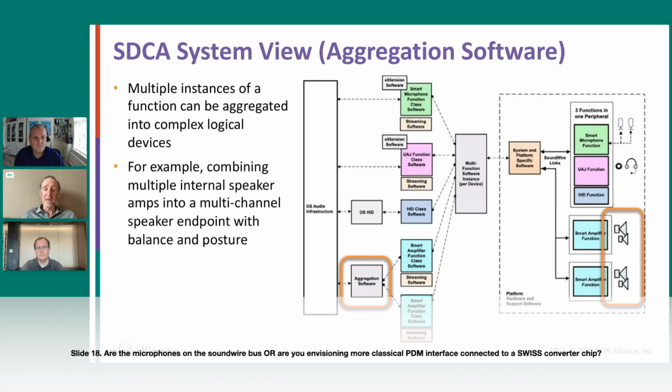In SDCA land, we call that a smart microphone function that supports multiple microphones. So you might have one package that supports the 2 or 4 microphones on your PC. It's already doing the PDM to SoundWire interface locally within the codec.